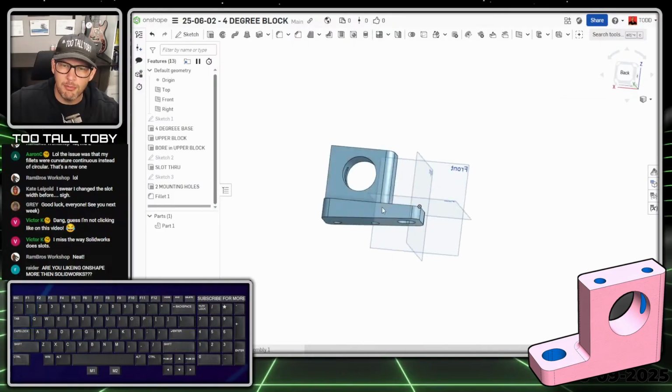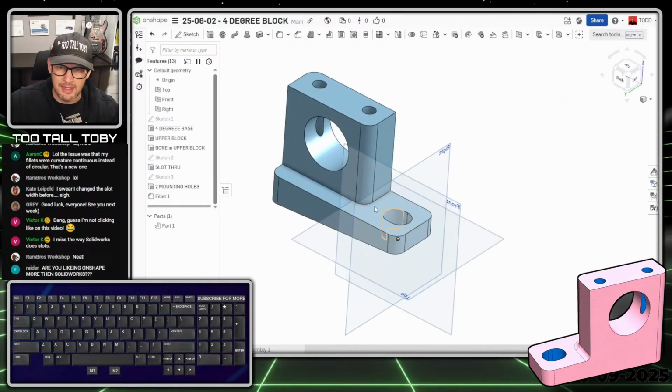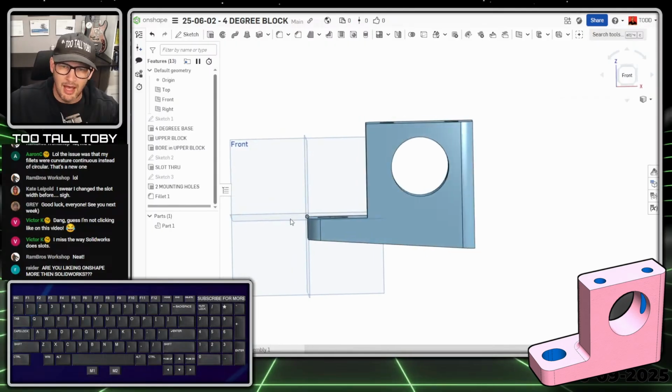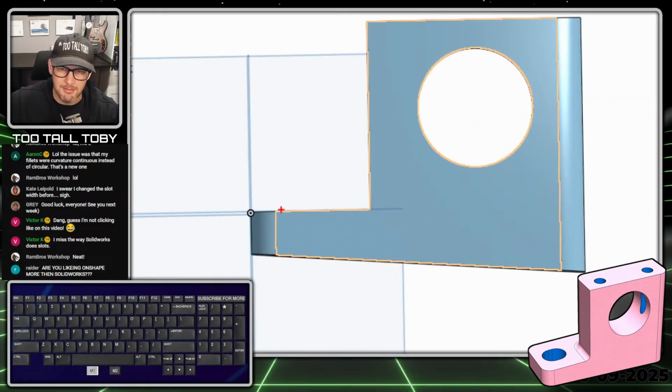So that gives me those 12 millimeter fillets, and then the only thing I need is for the toolpath. When you're machining a part like this, you're gonna have some type of tool that's gonna come in either from this side or from the top, and it's probably not gonna have a straight bottom. It's probably gonna be a rounded end mill. So that rounded end mill is why we end up with those radii in the corner there. You're gonna end up with a radius here from that rounded end mill.